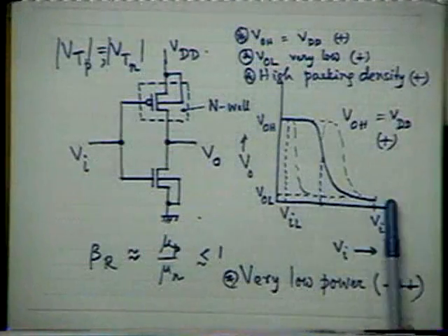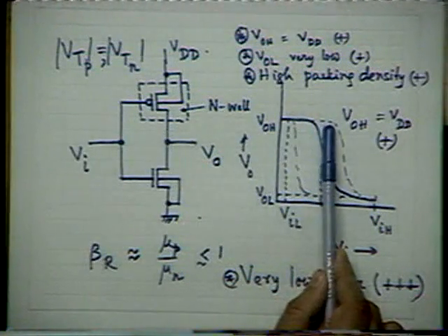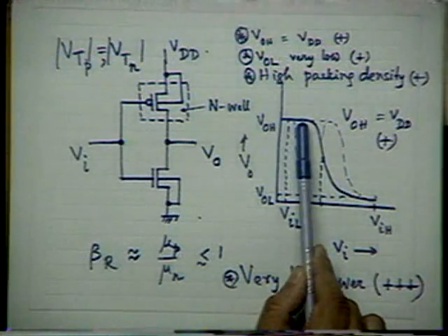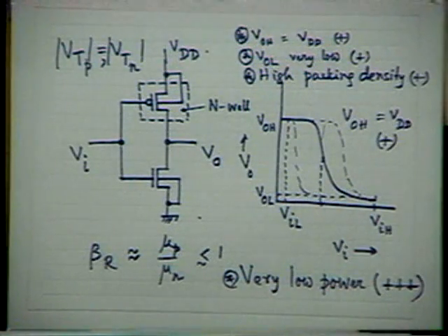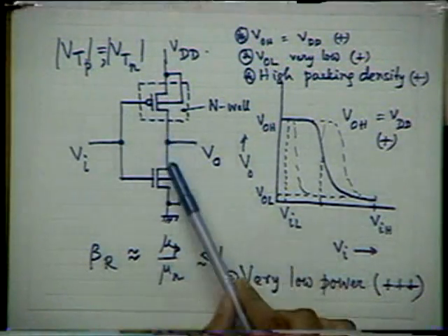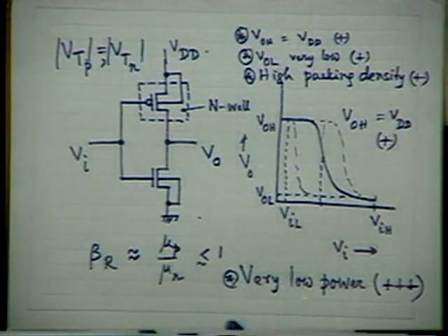But please note that for the proper placement of this characteristic, to achieve the same order of noise margin for both high and low states, and high noise margin, we have to make both transistors very similar in nature so far as their DC characteristics are concerned.